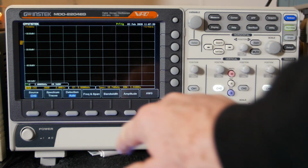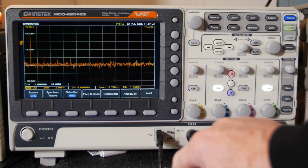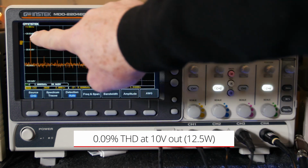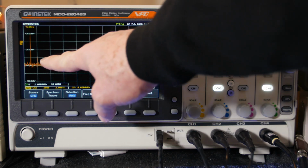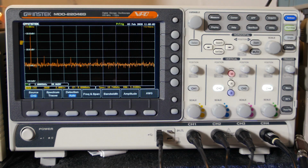Okay, now the other thing you'll notice, and I'm not sure what's going on there. The THD meter says 0.09% right now. So the signal is pretty high, plus 20. And so if you come down 20, 40, 60, that's 60 dBs from the signal. That's pretty darn low, guys.